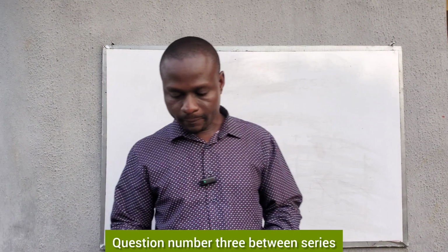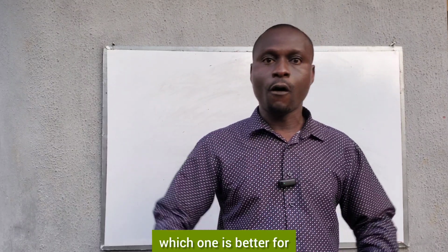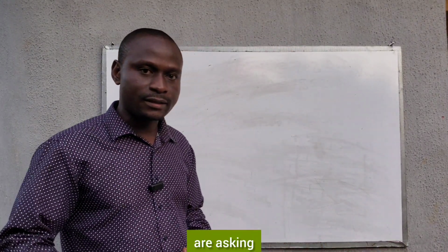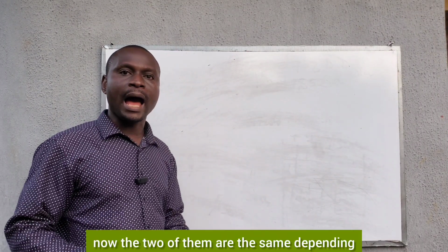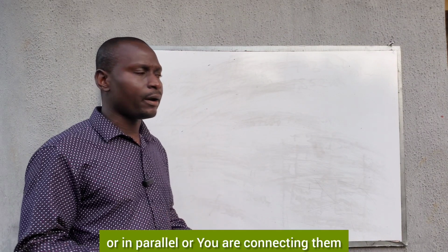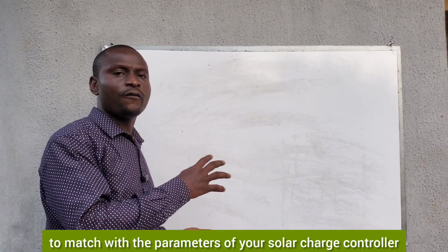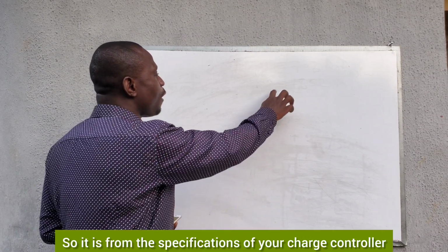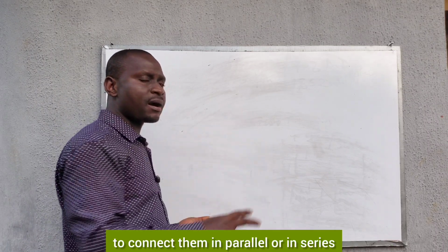Question number 3. Between series and parallel connection, which one is better for our solar panels? That is what many people are asking. Now, the two of them are the same, depending on how you connect your solar panels. You are connecting them to match the parameters of your solar charge controller and the battery bank you want to charge. So it is the specifications of your charge controller that will determine whether you connect them in parallel or in series.